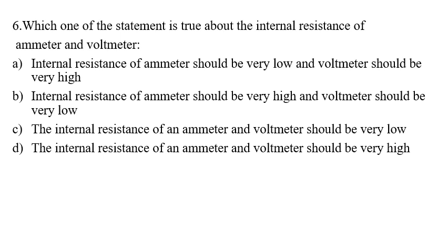We need to remember that in a circuit, ammeters are normally connected in series with the load or in series with the supply. The function of the ammeter is to measure the load current, or the full current which is flowing through the circuit.